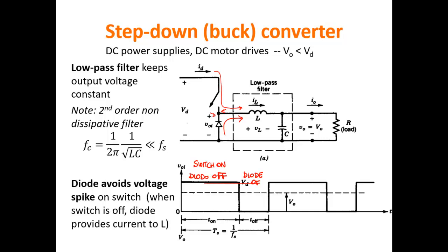So here, to be precise, the voltage goes to minus V gamma, which is the voltage with the diode conducting, the diode turned on. But for all our purposes we can approximate this V gamma with 0, because it's a much smaller voltage than VD, and we can make this simple approximation.